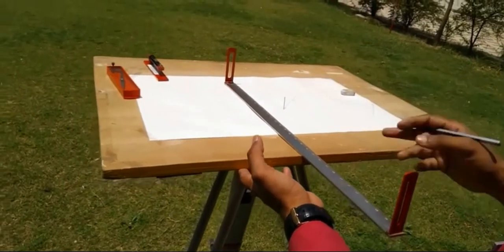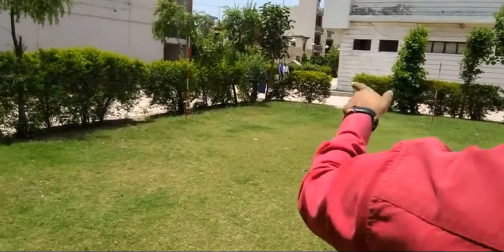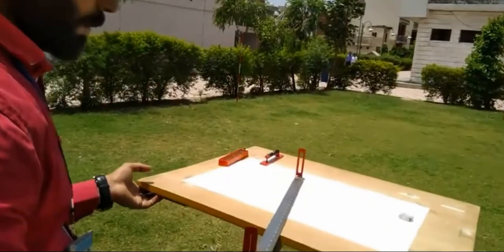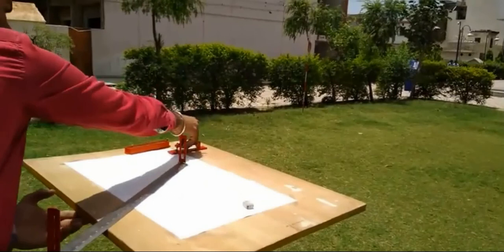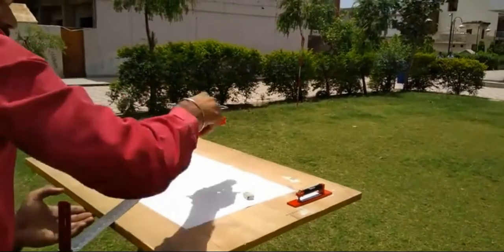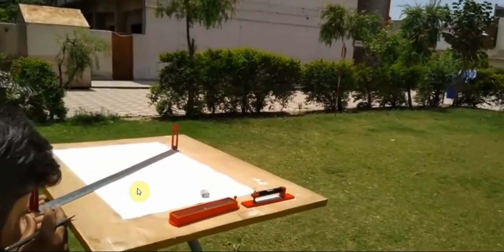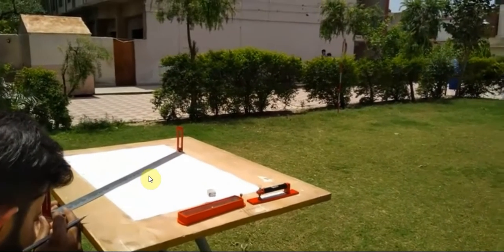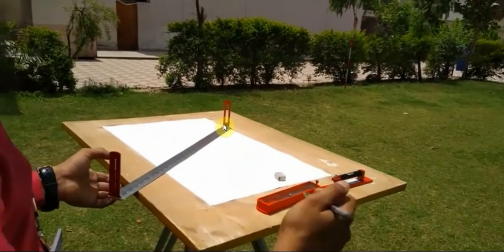Next, I will come to my third and last point. I'll keep the alidade against point O, since while sighting all the 3 points, I am keeping the alidade against point O. Now, through this narrow slit, I will make this hair intersect the ranging rod.